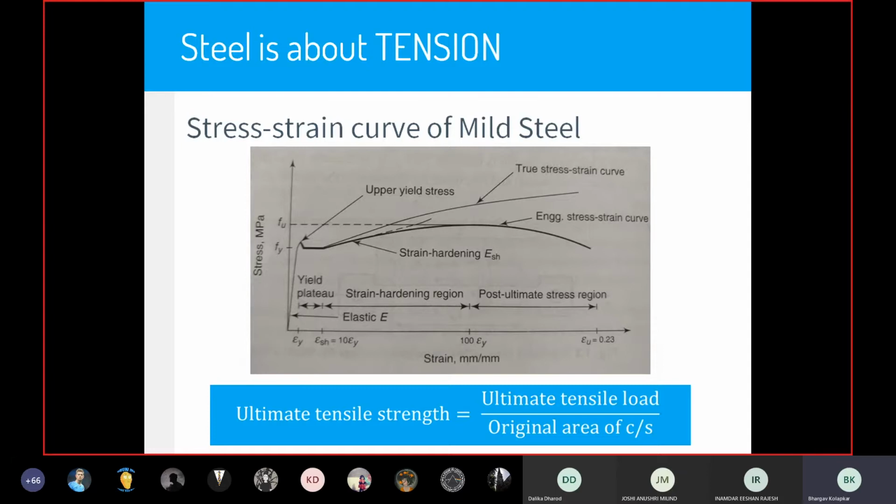For example, if I want to design a particular member for the live load, I will not consider the live load on normal days in a mall. I will consider the live load when there's a concert in the center of the mall, and the entire mall is filled with people. All the balconies have people. The balconies are cantilevered, and there are people standing all over, and that is the maximum load that is going to act on that particular section.